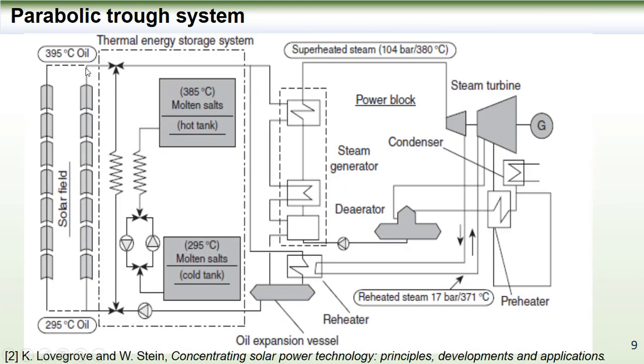This thermal energy is then transferred to the power block, where a heat exchanger produces steam, which drives a steam turbine to generate electricity. This oil acts as a thermal buffer to eliminate any temperature instability in the solar field, and allows steam and therefore electricity generation for a couple of minutes before any clouds can affect the power generation of the system.